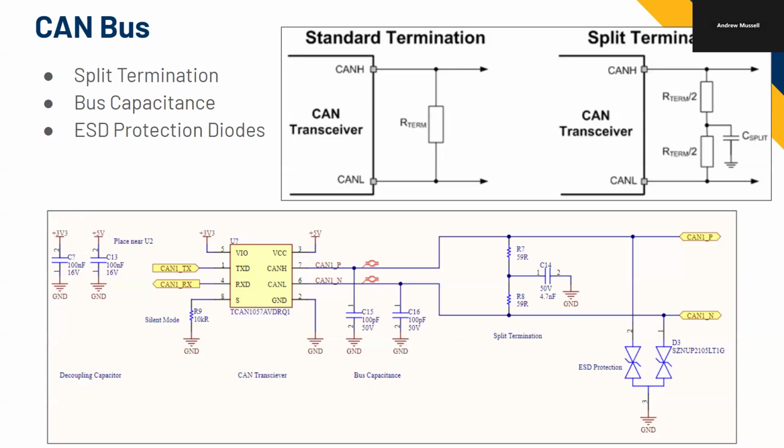Because if I need to add more capacitance to the line, remember we learned that makes it harder to drive the line, but it also makes it so the line won't move around as much to random variations and oscillations. I added those so that there's pads for you to add components if it's something we wanted to have to try to smooth out the bus.